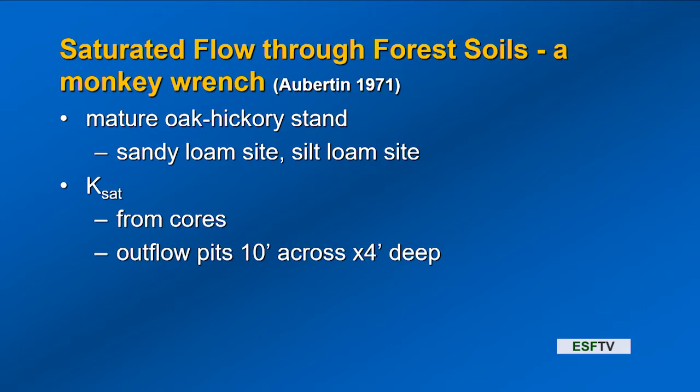And some of the measurements they made were Ksat. So one of the ways to measure Ksat, the rate of saturated flow, is to use a core. So take a core, bring it into the lab, run water through it, measure how long it takes for that water to move through, and then compute a Ksat.